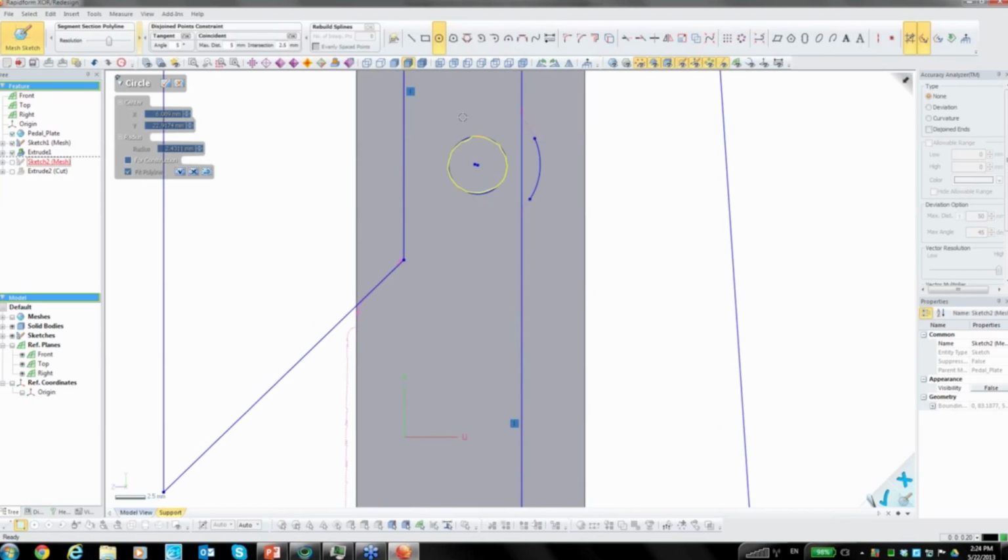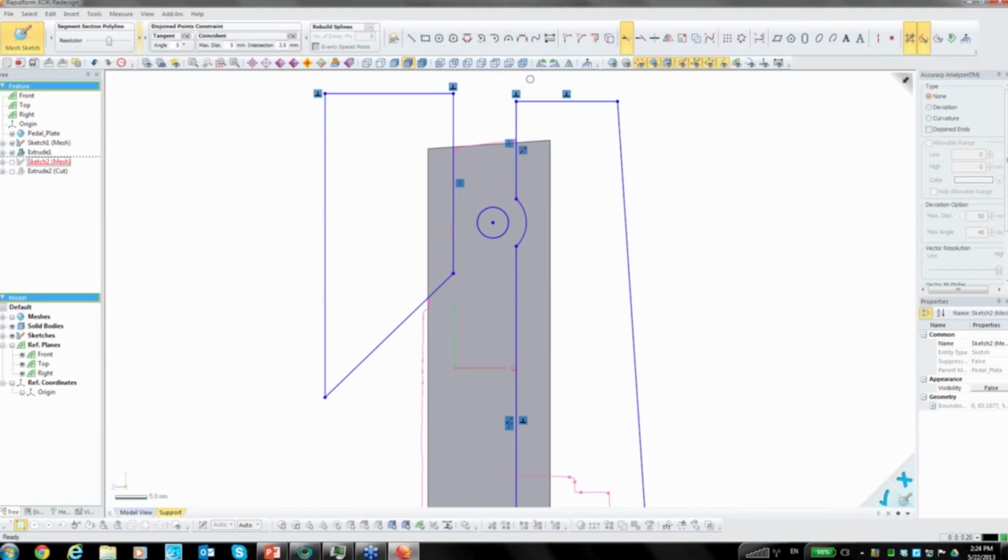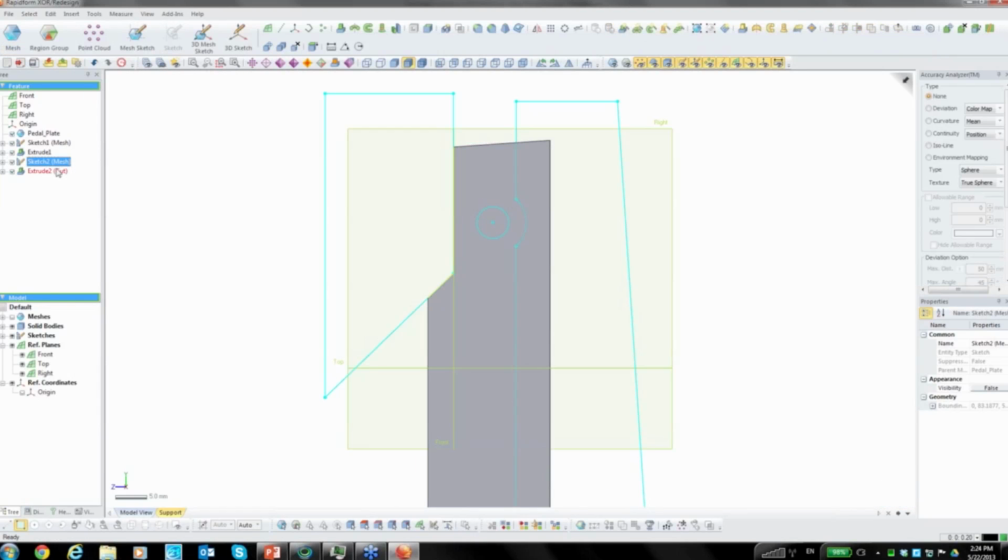I'm going to add just a couple more details here so it looks complete. You can see I can fit geometry right to the scan, such as that circle. And I can snap things together, better fit the shape. We won't spend too much time on this. I'll add a couple of dimensions. So instead of 2.43111 something millimeters, I'm going to say the hole is probably intended to be 2.5 millimeters, 2.5. And I can make those adjustments to the design all in one shot.